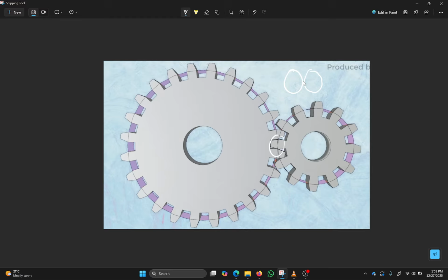Now there is another circle that is a little above the dedendum circle. If this is the bottom circle, the dedendum circle, just a little above that there is another circle called the clearance circle. The purpose of the clearance circle is this: here is one gear, and to pair it up I will have another gear meshing with it.